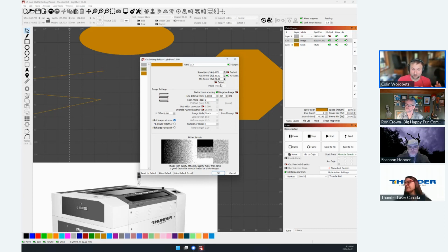Now, with CO2 lasers, there's also a minimum trigger amount. So if you fire your laser at like 5%, most lasers will do that. But if you try to fire at a 3 or a 2%, there's a threshold that you need to pass before your laser will actually fire. So trying to dip below that 5% range, you'll have to test on every individual laser to figure out, okay, what will my laser actually fire at? That scales with your tube power as well. So with a 130 watt tube, that value is higher. So you'll get better results on the low end with the lower wattage tubes, which is why sometimes it's recommended for doing precise or low power engraving, you use the lower wattage tubes.